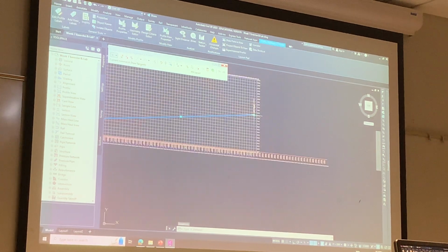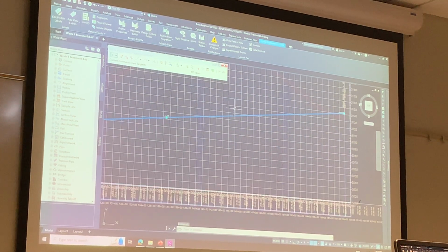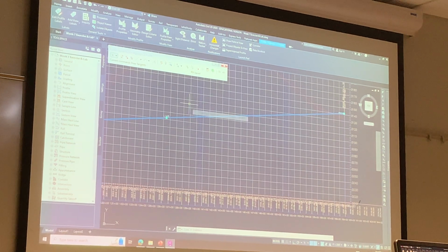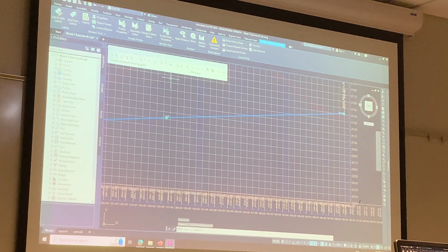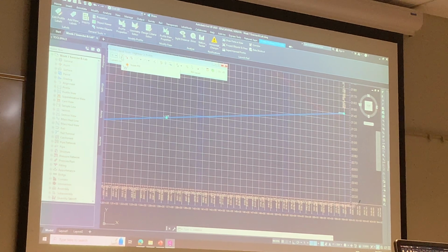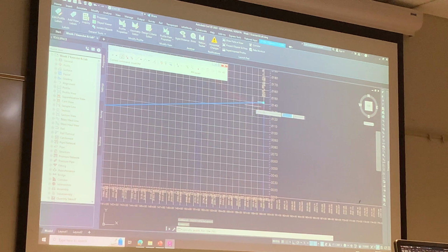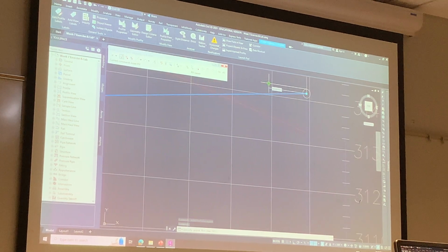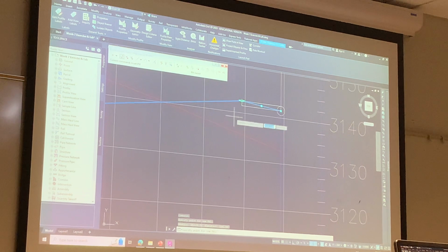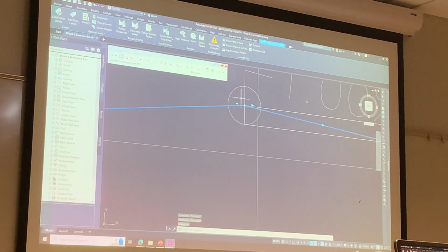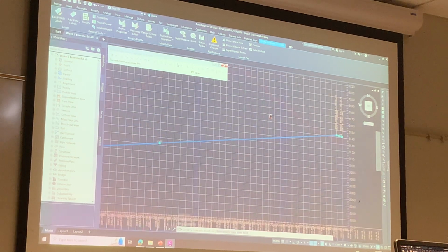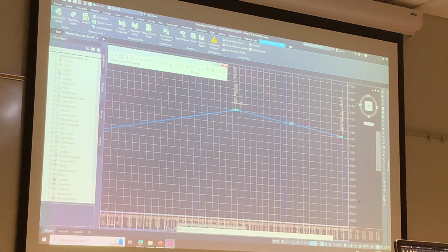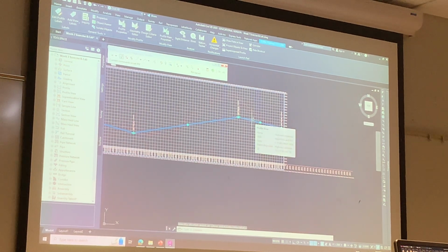Now what I'm going to do is once again select my profile, right click, and edit profile geometry, making sure I'm editing that profile again. If I click the second button on the left of this toolbar, insert PVI, what if I placed a PVI right there? And if I escaped out of this, clicked on this drag arrow, and dragged it this way, now I can make it as long or as short as I want.